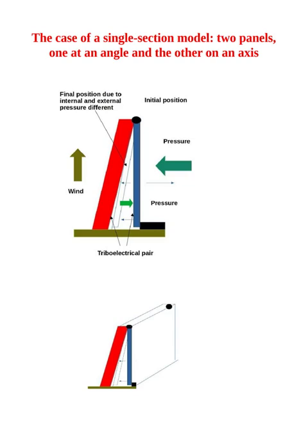The pressure drops in the narrow part between the first and second panels, while the external pressure remains unchanged. The pressure drop is caused by the Venturi effect. Under the influence of the pressure drop, the movable panel is adjacent to the fixed panel. The narrow space between the first and second panels closes.